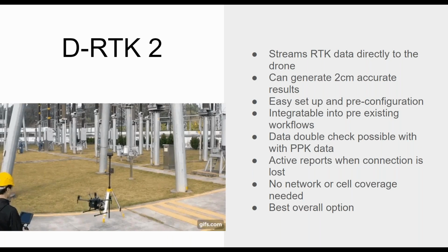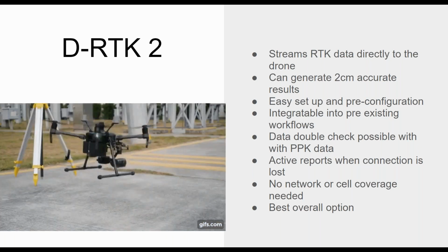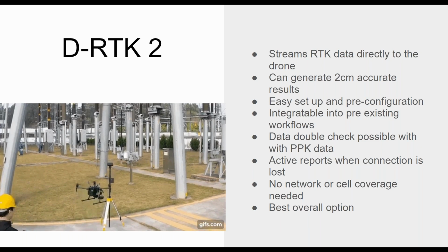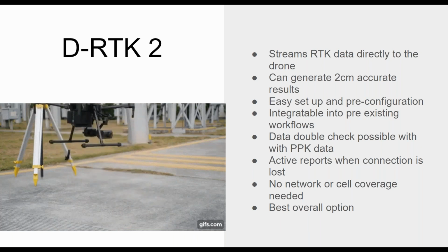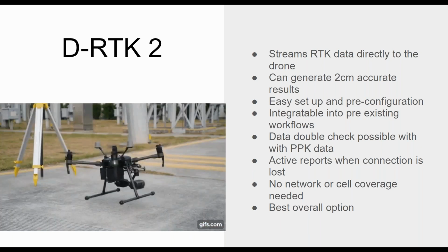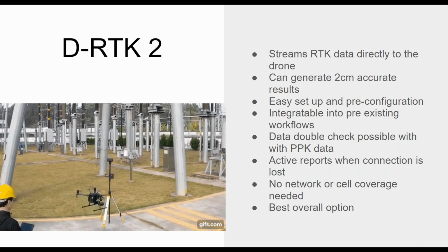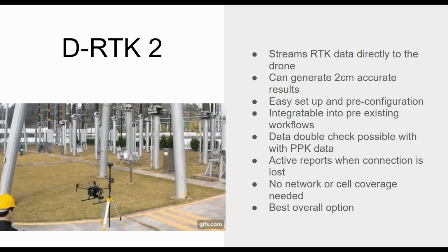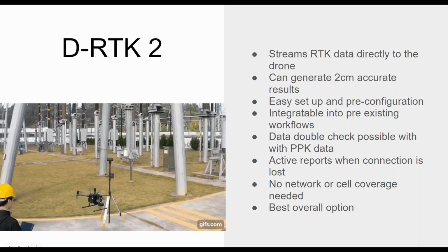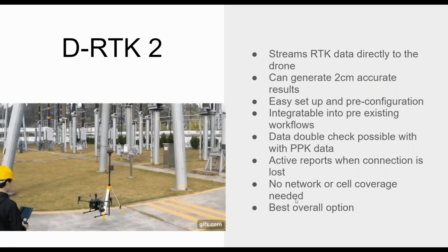Some of the only downsides to this method is the fact that you have to purchase and learn how to use a new base station. This often means bringing 2 different base stations to one job, one for flying and a second one for taking PPK data as backup, which I always recommend.